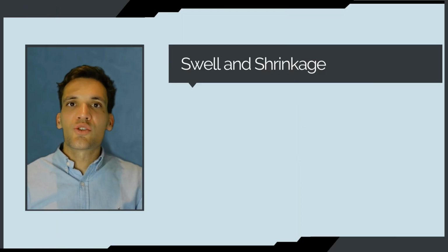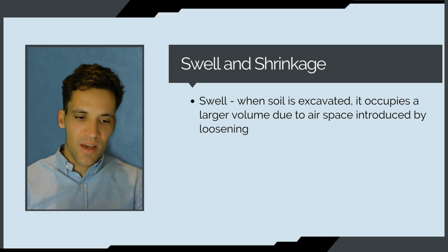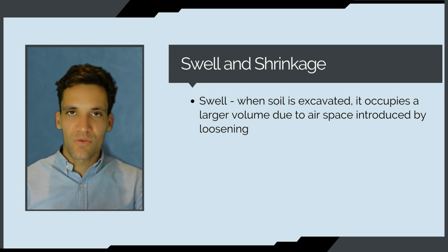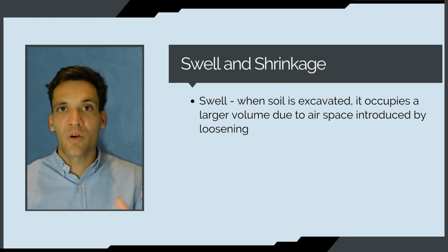The next is swell and shrinkage. Swell is when the soil is excavated, it occupies a larger volume because it's not compacted. So when you dig up soil from the ground, it loses its compaction, so it swells.